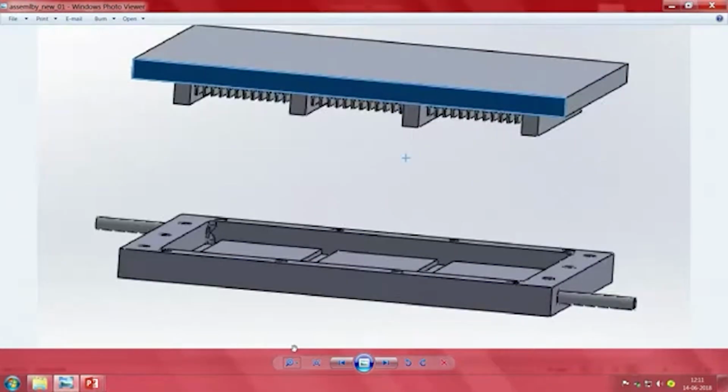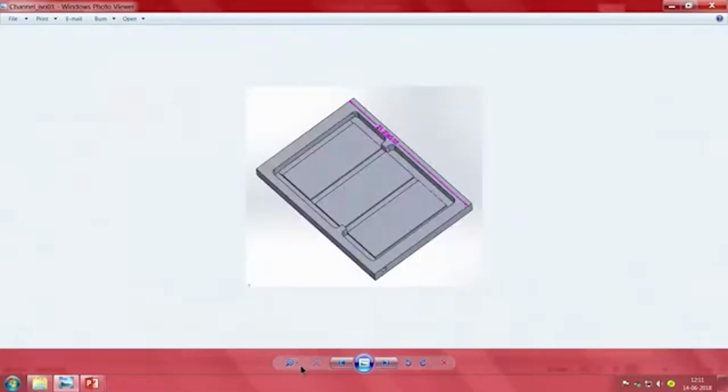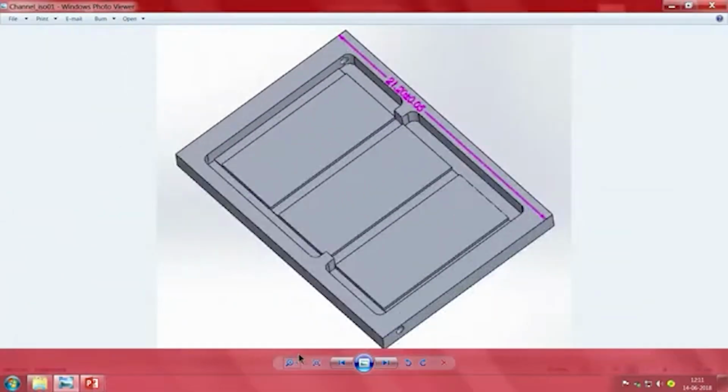See here, this part of it is the heat sink, and then some channels have been made here, and you see this is thicker and it blocks here. In one of these drawings, water is supposed to enter here, and this forms an inlet header, same as you will find in a passive solar water heater.